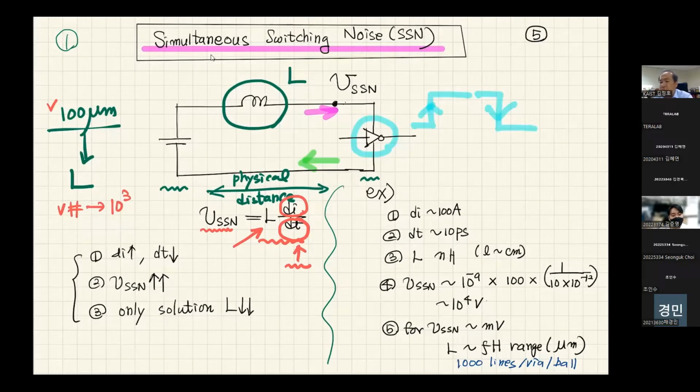The second thing is we want to minimize the power supply noise. The only way to do that is to reduce the inductance, and effectively we can reduce that by the number of interconnections. That's why I keep saying that the number of interconnections in your semiconductor and computer system will be millions or more in the near future. This is the nature. This is not an engineering principle. This is a physics principle.